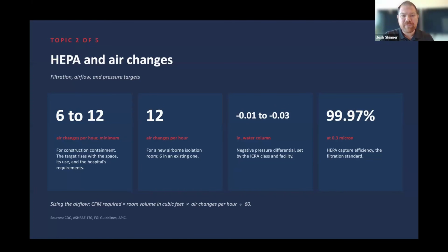Piece number two is metal frame has got to be everybody's standard when it's anything to do with hospital and patient care. Wood frame or particle board HEPA filters are less stable, less structurally sound, and they just have more problems, and you get leakage, and then not all the air is going through the HEPA, so therefore you're not hitting the efficiency you needed to. So that's piece one. How do we start off sound?